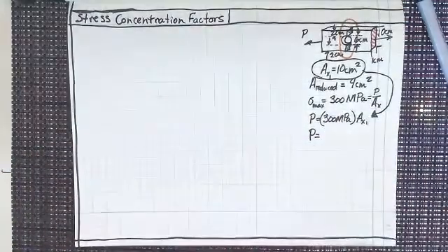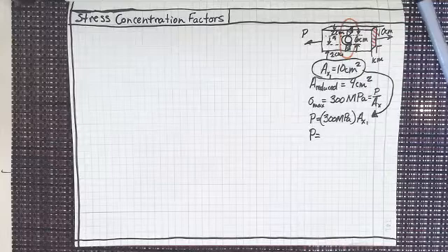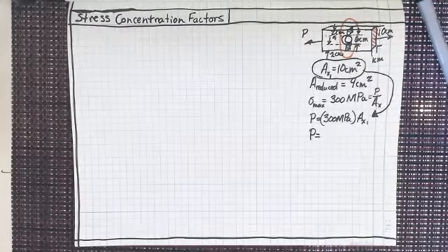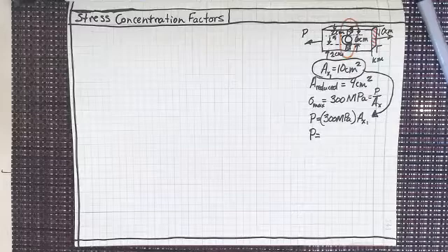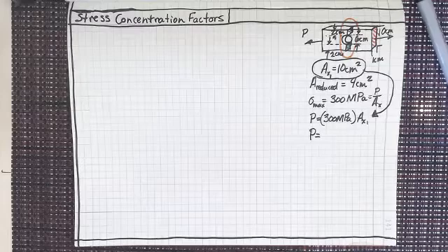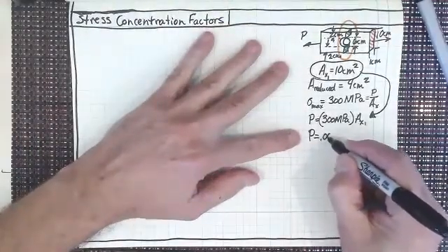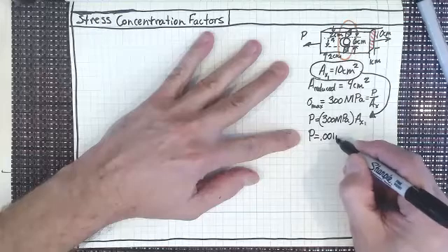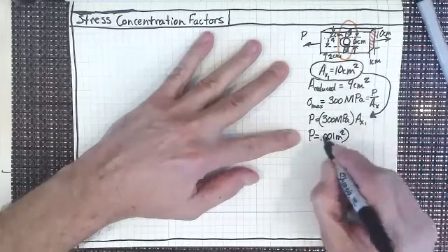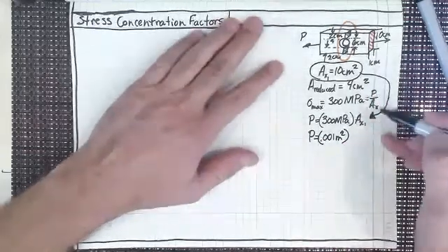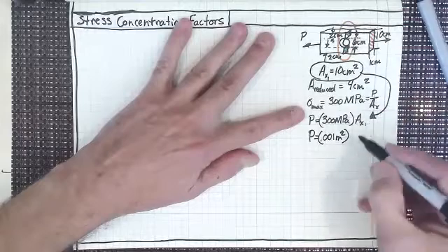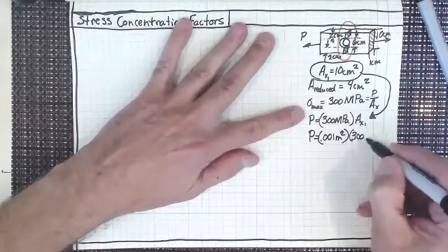And of course, like I said before, 10 square centimeters, I'd have to divide that by 10,000 to get square meters, wouldn't I? And of course, that's 100 centimeters to a meter, squared gives me 10,000. So 10 divided by 10,000 is going to be 0.001 square meter, right? So that's what AX1 is. And then I'm going to multiply it by the 300 megapascals.